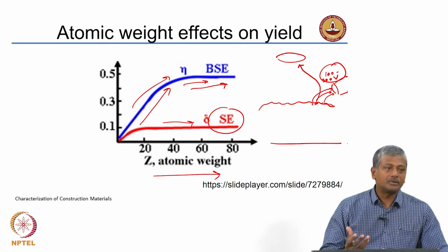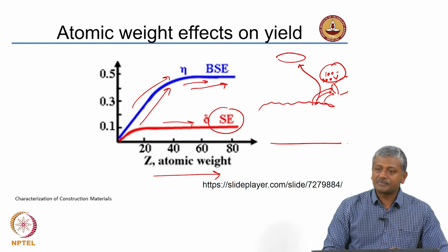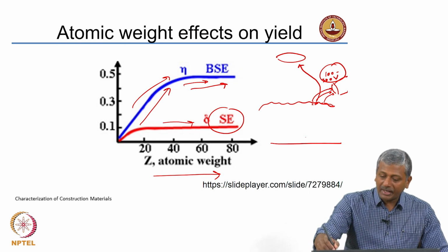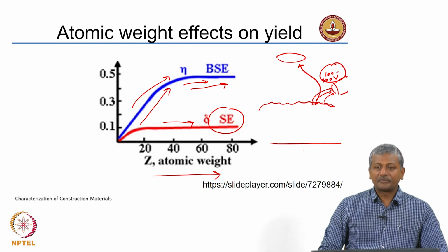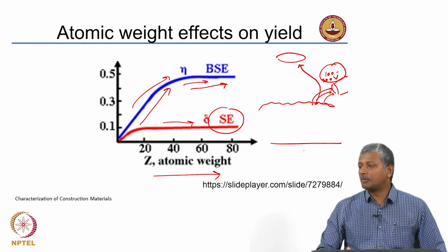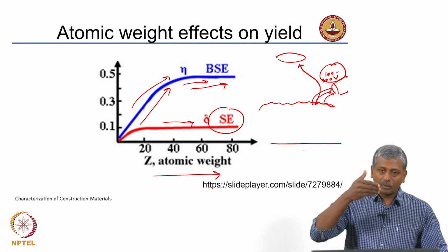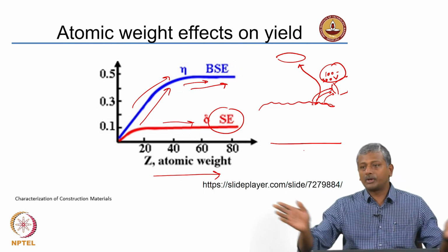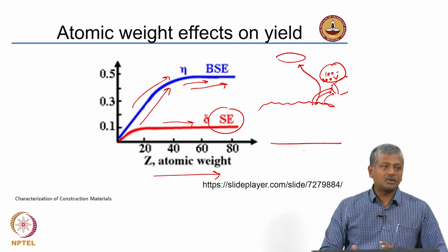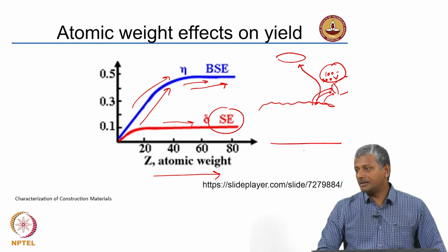You will not be able to appreciate that if the specimen is flat, okay. But if you are trying to observe the flat specimen, or rather a fractured specimen with the backscatter, then again you have a problem, because you do not really get a proper scattering, all your electrons are going towards the side because you do not have a level surface. So, for each of them you need to have sample preparation done in a different way.